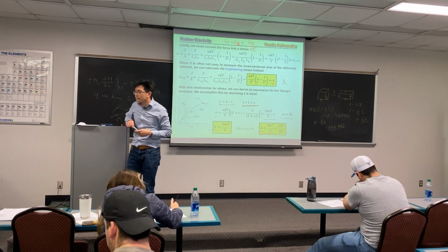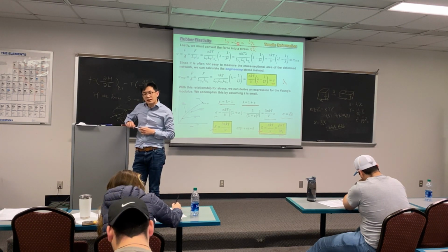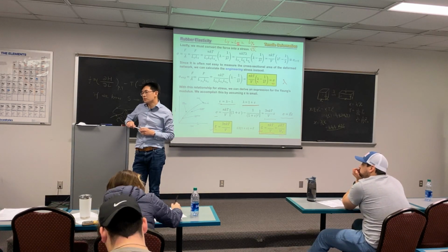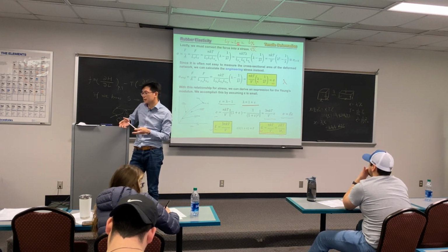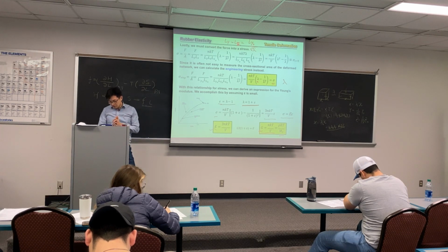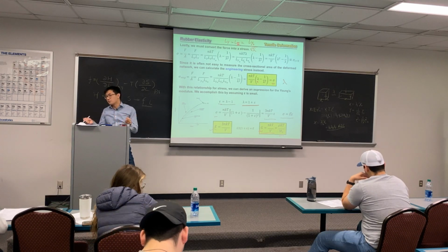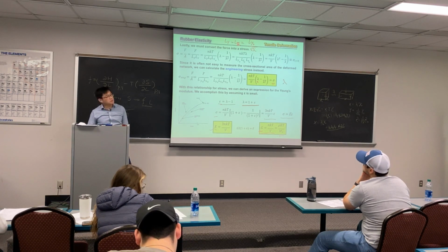Can this relationship work for glassy networks as well? I think a glassy network will be hard to deform. There is one assumption: when you want to deform this, you are already in the mobile state. That's why an elastomer typically has a Tg below room temperature, so the chain can be deformed. For the glassy state, I think it applies, but you wouldn't be able to deform it. So G would be inversely proportional to Mx.